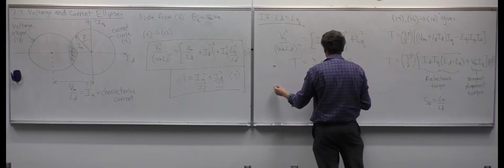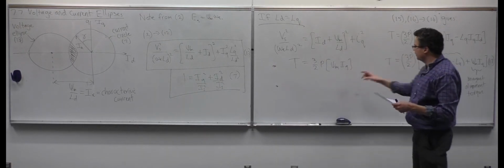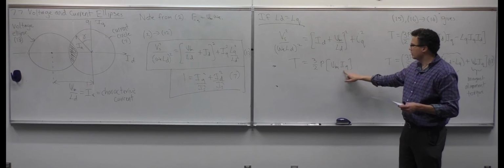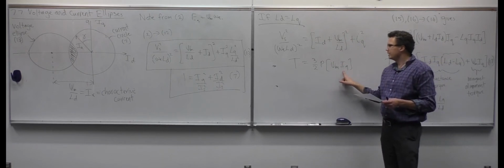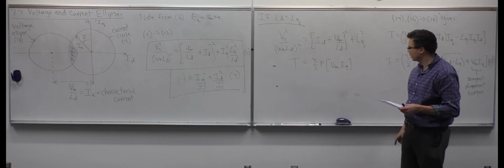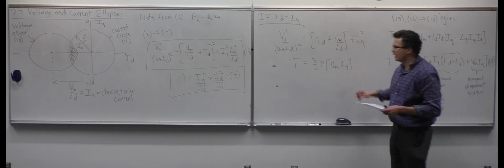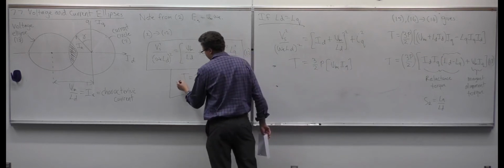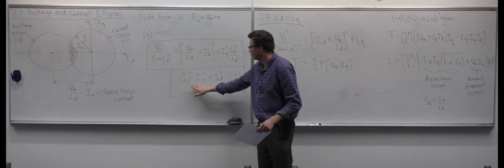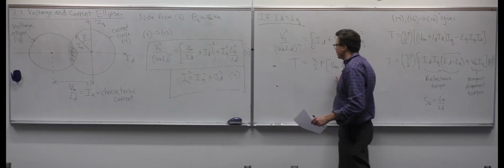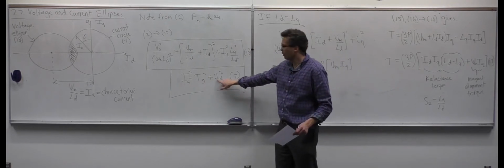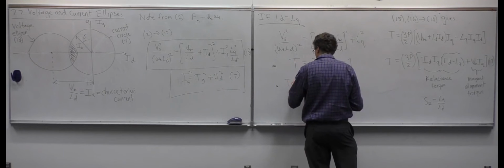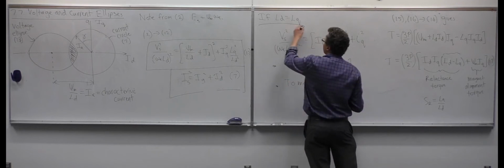Now thinking about only the case where we have LD equal to LQ, what would be the value of the ID current that maximizes the torque? Remember that the current is limited by equation 7. So if IS is fixed and the torque is only dependent on IQ, if we want to maximize the torque, we would like ID to be 0. And this is the case if LD is equal to LQ.